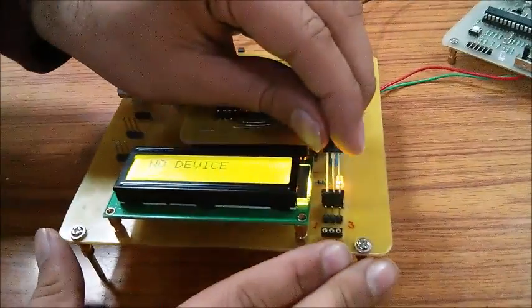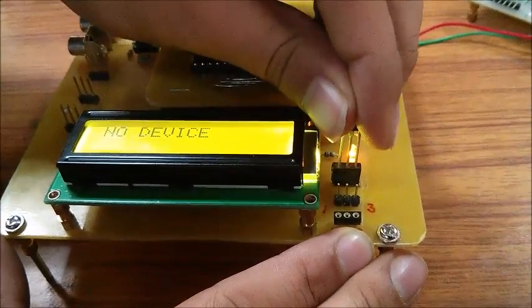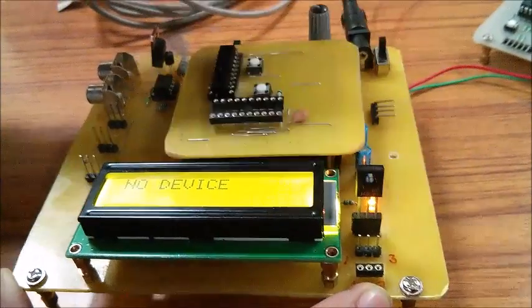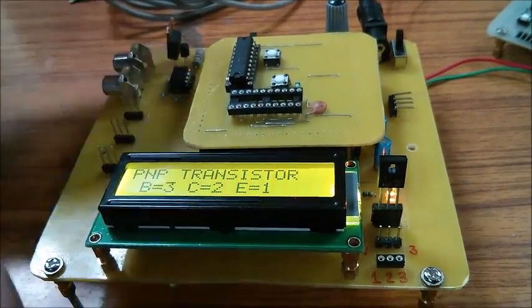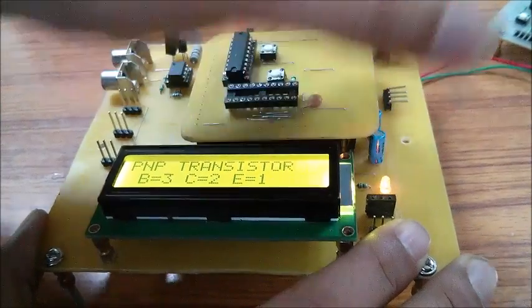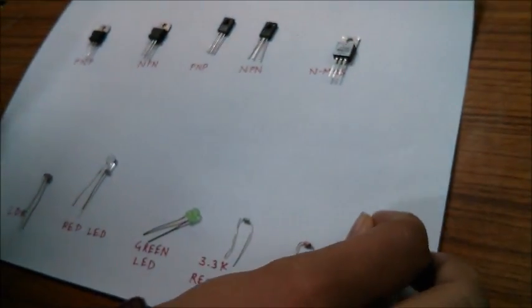Now we will demonstrate the use of device tester circuit. We have taken a PNP transistor AD140, placing the transistor in the test socket and pressing the reset button. The circuit takes 2 seconds and displays the result of DUT. Here you can also notice that the specific LEDs of the DUT have been shown with respect to the pin mapping indicated on the board.